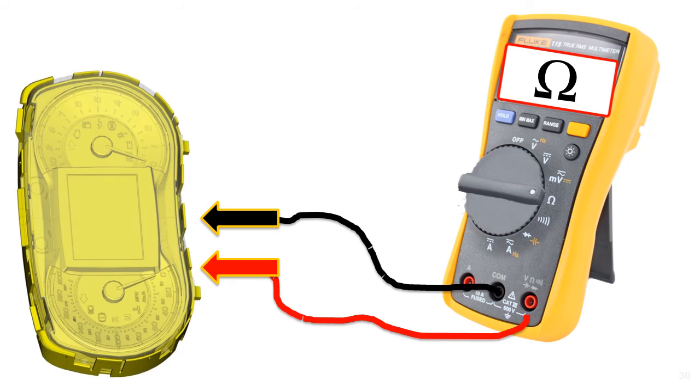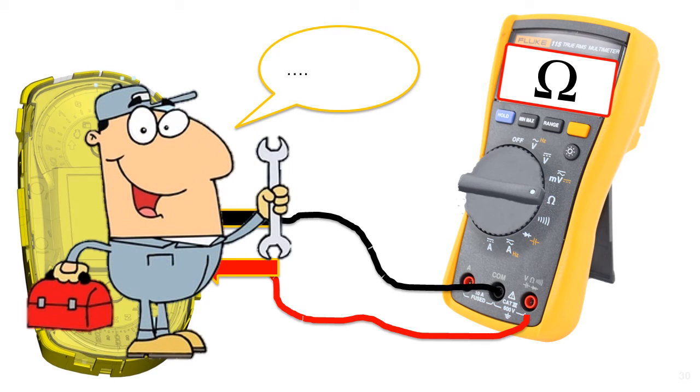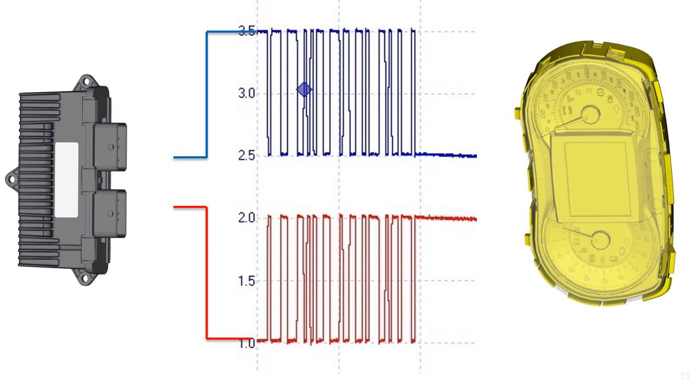If you suspect a defective module, measure the resistance across the CAN high and CAN low terminals. If the module has a terminating resistance in it, you should measure close to 120 ohms. Modules without resistance should measure in the kilo ohms. Any modules with a resistance below 100 ohms have a problem and can prevent communication on the CAN network. In some cases, it may be easier to probe the diagnostic connector and unplug all the modules except the one to test.